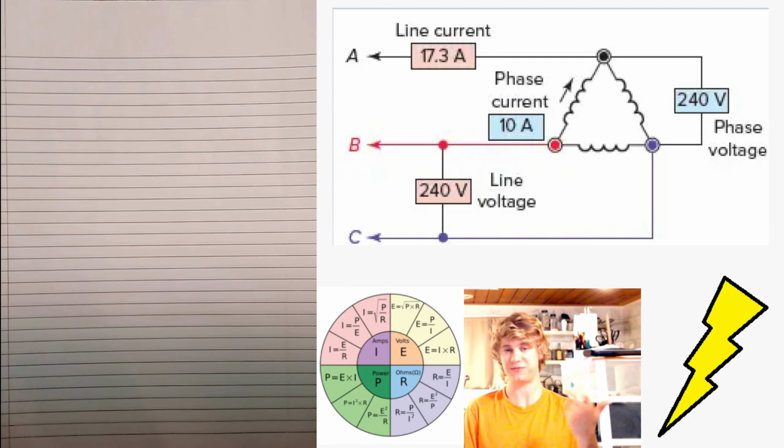So first, a 3-phase system is going to use 50% more wire. Second, the 3-phase system transmits 73% more power. Power delivered by a single-phase source is pulsating, like we're learning with the magnets, whereas the power delivered by a 3-phase system is relatively constant. And then next, the actual size of the motors. 3-phase motors are much smaller in size than comparable single-phase motors.